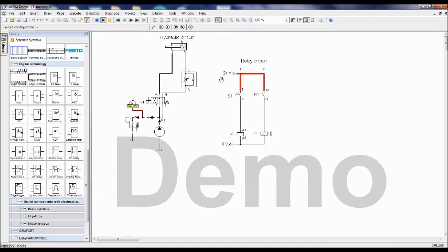Okay, so now see, there is no electrical continuity here. The line number 1, line number 2 also there is no electrical continuity. So if you press the S1 switch, current flows to K1. When K1 is on, the contacts belonging to K1, which if closed will become open, and if open become closed when the coil is on. Since we are using a normally open contact, when the coil is on, the contact becomes closed. Observe this, so the solenoid is on when the switch is operated. This is controlling the cylinder using a push button.